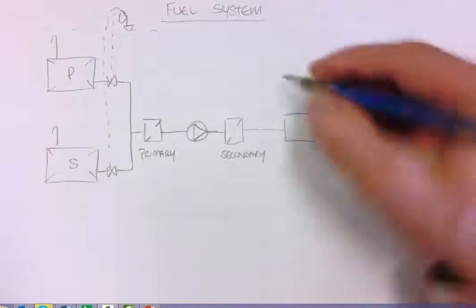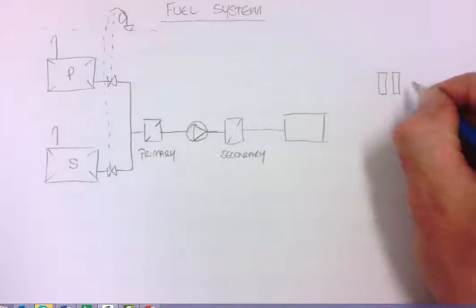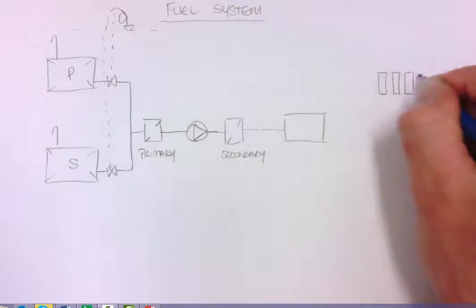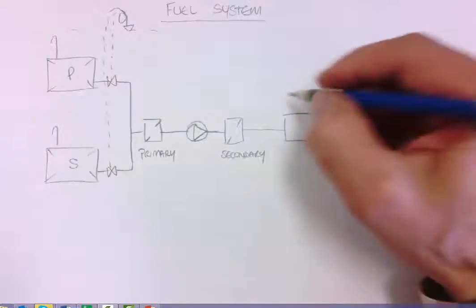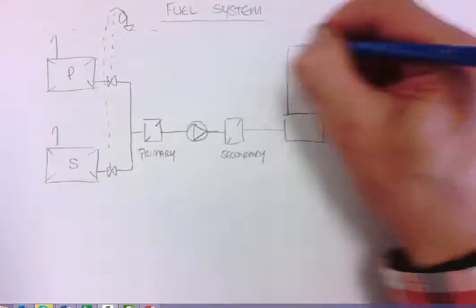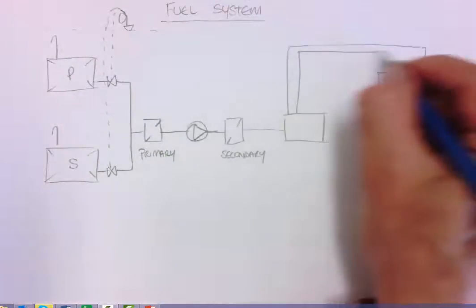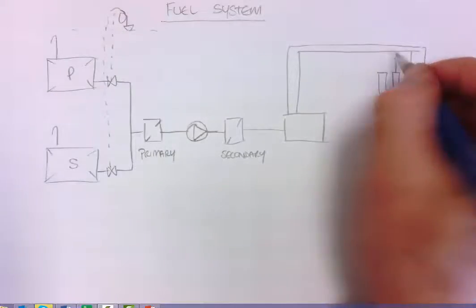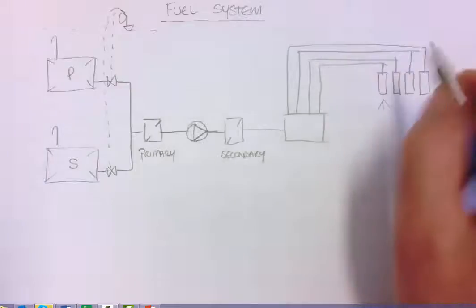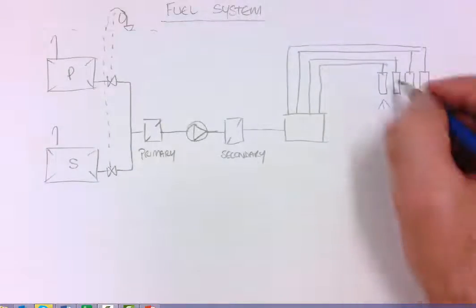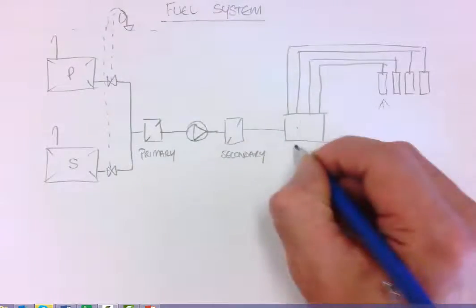Our injection pump is a high pressure pump, which delivers injection pressure so that we can get finely atomized fuel. Like I said, we'll cover that in more detail with diesel engines. I'm just looking at trying to put together our basic system. Here are our high pressure fuel lines, our injectors, and we always supply more fuel than is needed with our injection pump.